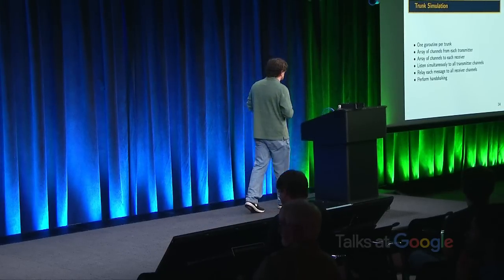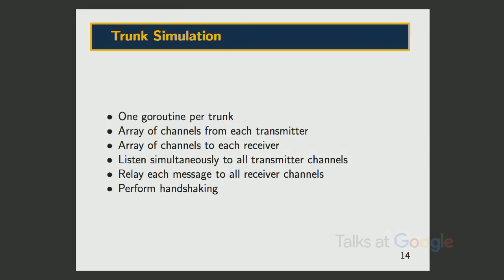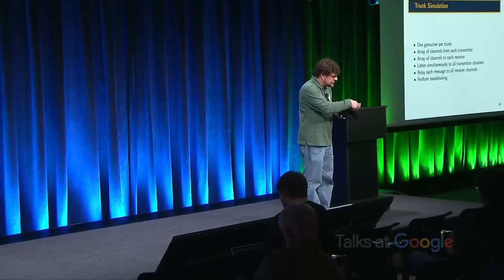So this is kind of the discussion about how those trunks work. Now let me mention the handshaking. In the original machine, when the clocking unit, the cycling unit, transmitted, say, a central programming pulse throughout the machine, then of course each unit would respond to that. It would potentially, as a result, send out other signals. Now, the design of the machine was such that before the next pulse, the next cycle of that 100 kilohertz clock, we could rely on all of the circuits having finished what they were doing with that first pulse.